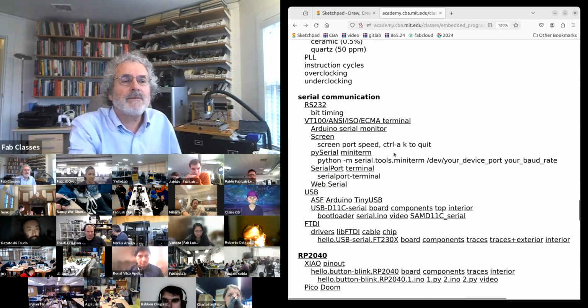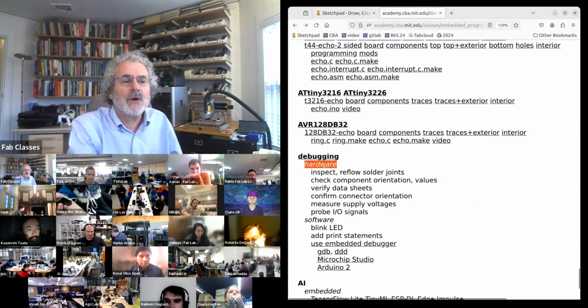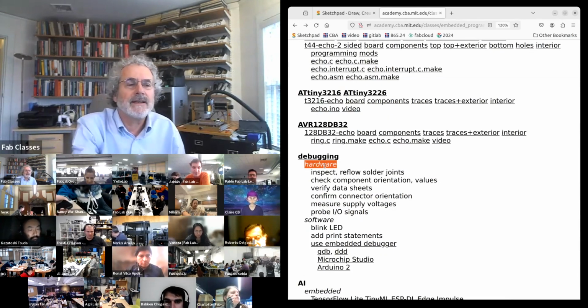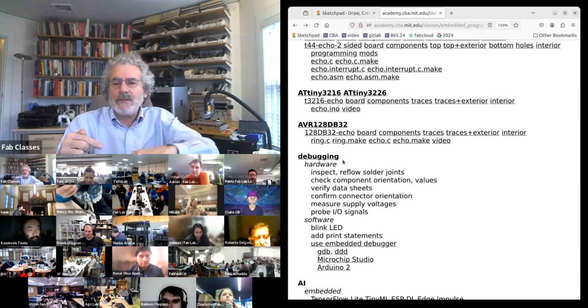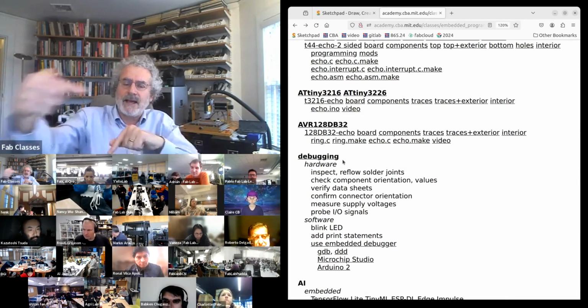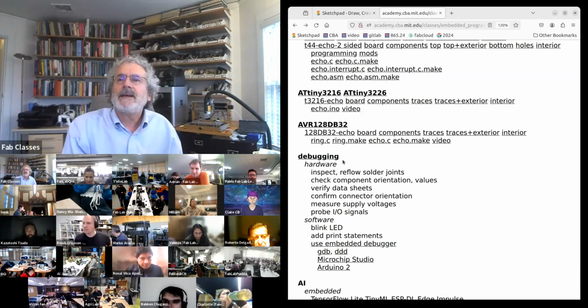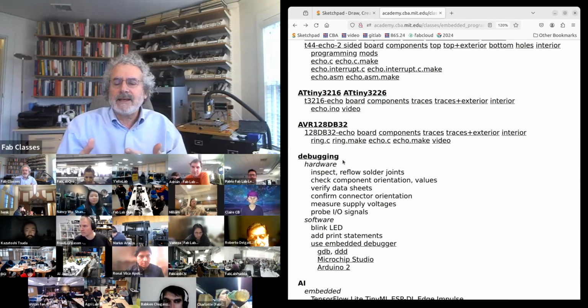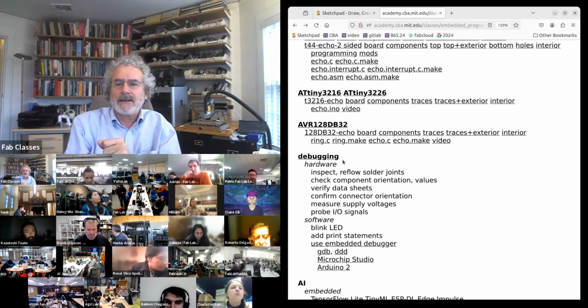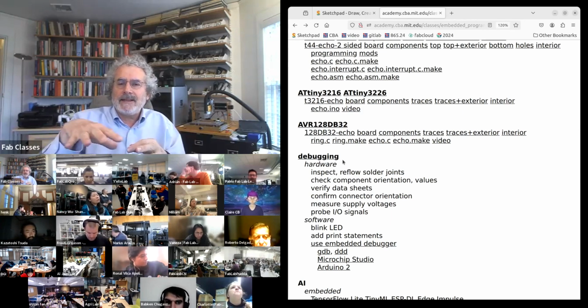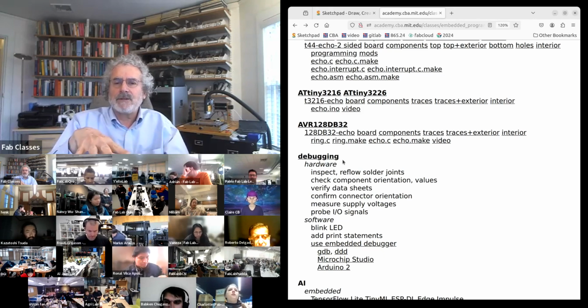And then I'd say the other really important lesson is what's so tricky about the debugging is, let's say you just want to read the button into the processor and have it control the LED. If it doesn't work, the mistake might be in your program. It might be in how you loaded the program. It might be in the connection of the processor to the board.